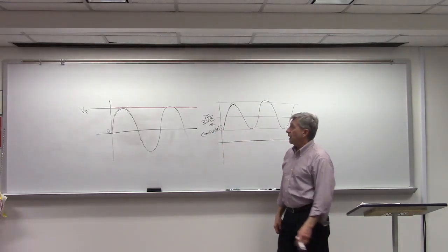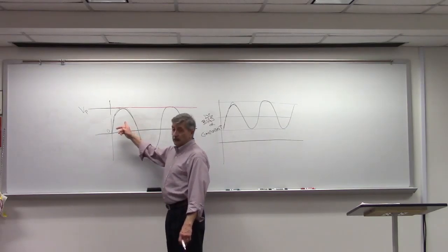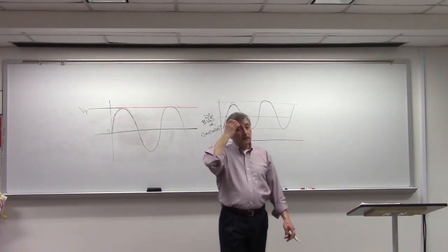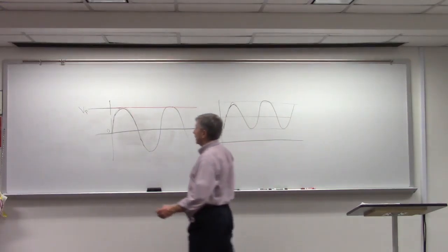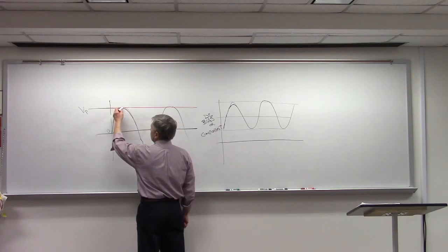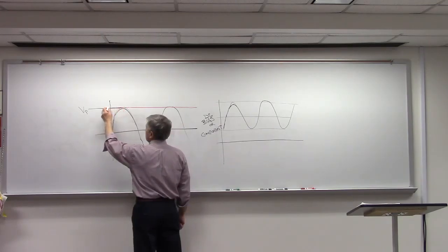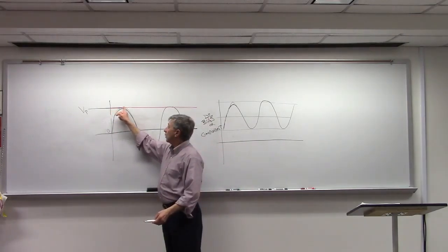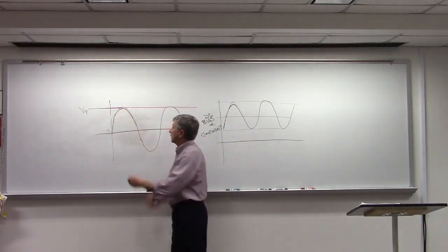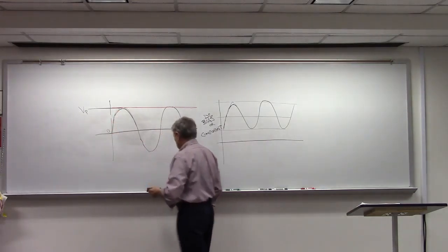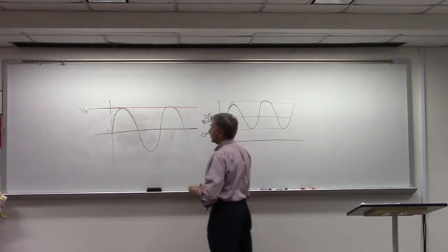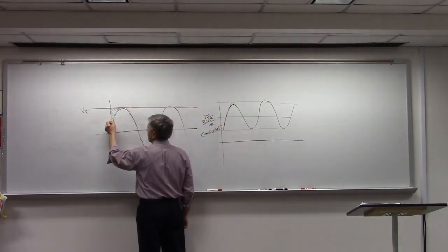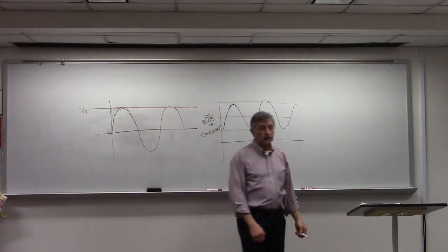intuitively you're going to see that the light bulb powered from the alternating current is not going to shine quite as brightly as the direct current, because there are places where, for example, right in here, the DC source is providing a constant power throughout that whole cycle from here to here, but the alternating current is approaching a maximum value and only reaches a maximum value for an instant, and then starts to drop down.